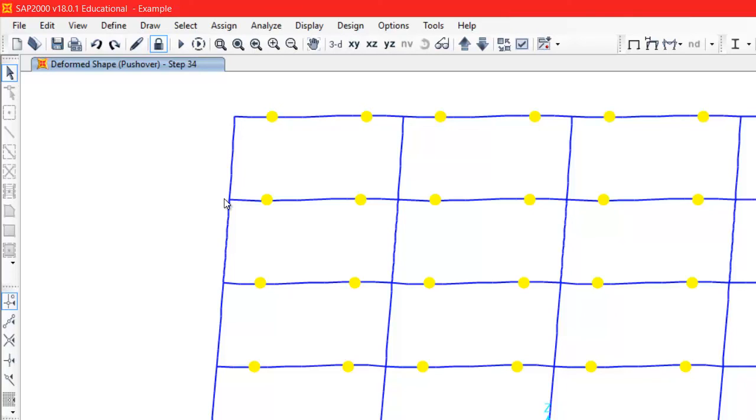If you want to model the panel zone, how can we connect the beam and the columns to the members? No, it's okay. This is the column, and then I have something like this. I have a node here, and then another element, another element, another element. Then I have here just a node connected fixed.